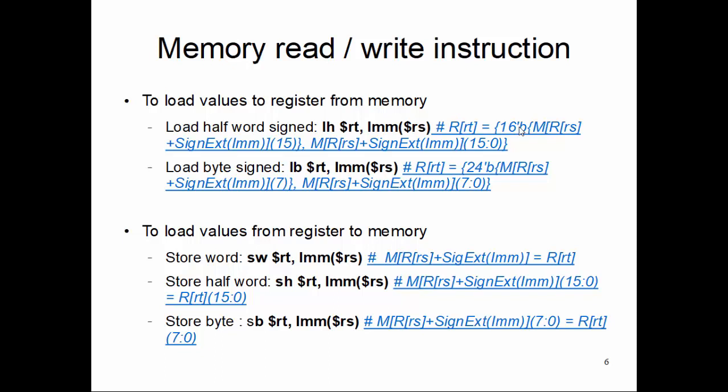So you really need to use these carefully in your program, depending on what type of value you are trying to handle, whether an unsigned value or a signed value. If you ever need to do a byte or half word operation, you should be careful about what you use. Do you use LBU or LB, LHU or LH?